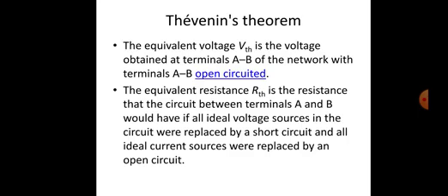Thevenin voltage: the open circuit voltage that appears across the two terminals is the Thevenin voltage. In circuit theory terms, the theorem allows any one port network to be reduced to a single voltage source and a single impedance. The theorem also applies to frequency domain AC circuits consisting of reactive, inductive, capacitive and resistive impedance.